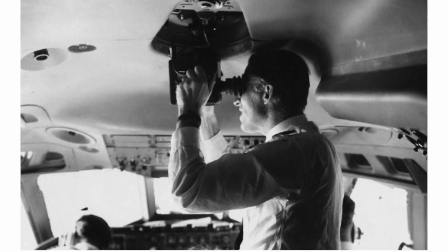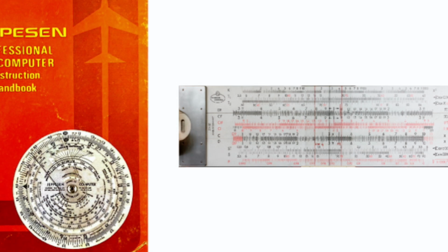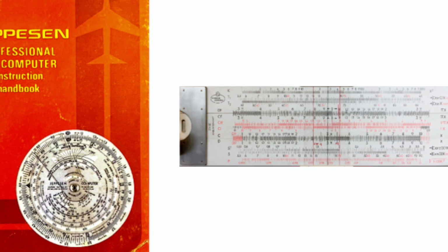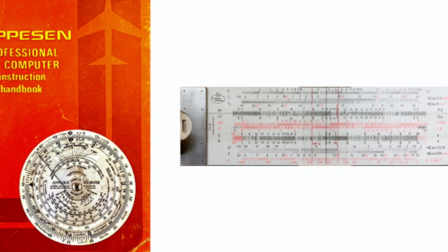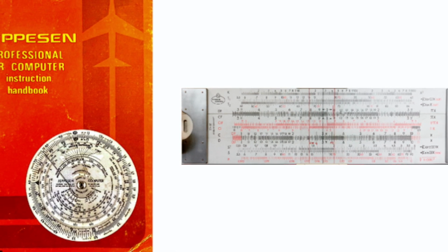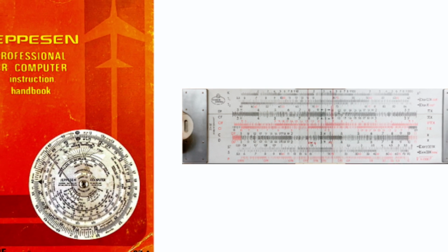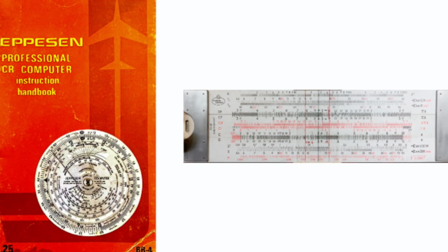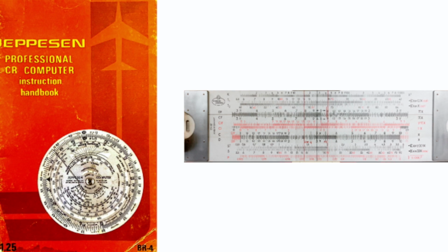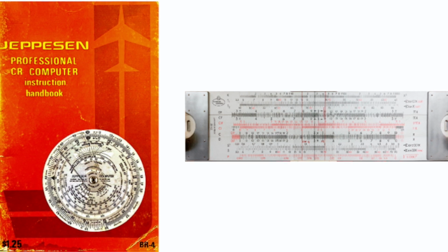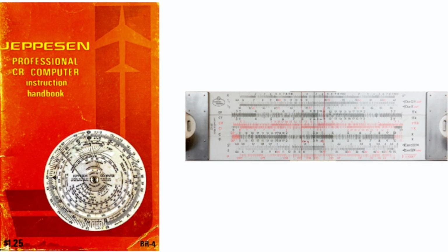Navigation over land was done through fixes, taking crossing lines of position derived from these radio indications, or distance to and from a station, as the dual frequency transmitter in the VHF frequency range developed. All the progress and everything was calculated using the computer, the analog computer shown here. This computer, the round one, is basically an endless calculating rule, like the one once used by engineers. Those were analog mechanical computers, as they transform a physical measure into numbers, giving results by opposing related measures.